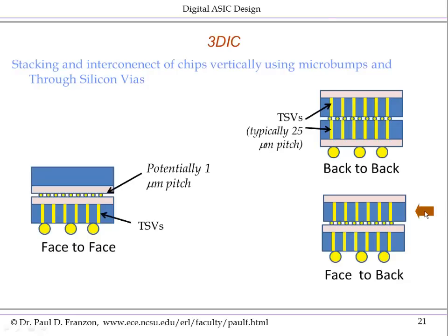So one thing I talked about a slide back, and also impacts the discussion on the previous slide, is the use of 3D IC technologies. The idea here is you can make two chips face to face. These are the silicon plus interconnect layers. This is the CMOS wafer underneath. You can make two chips face to face at a very tight pitch and have a very low power interface vertically.